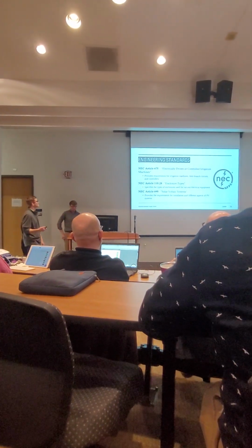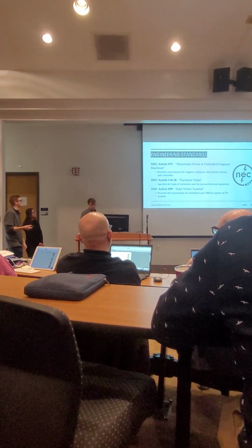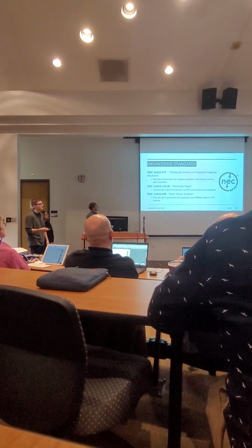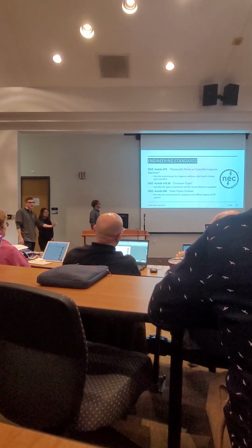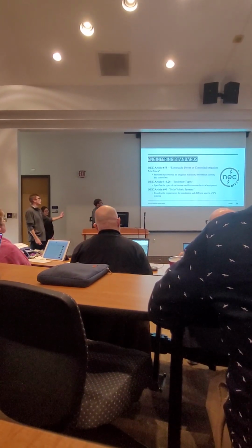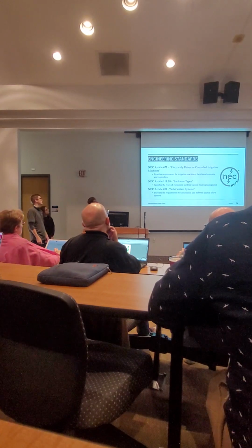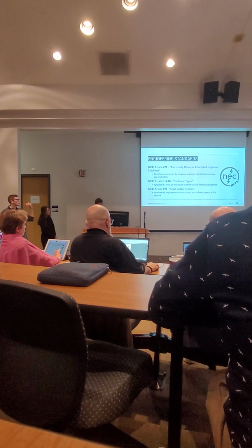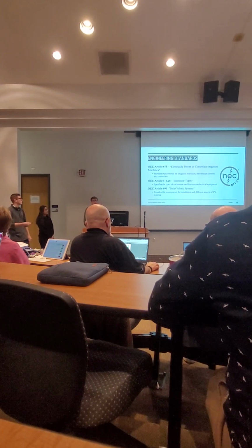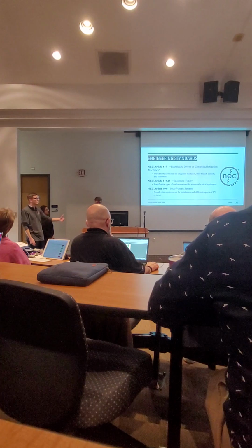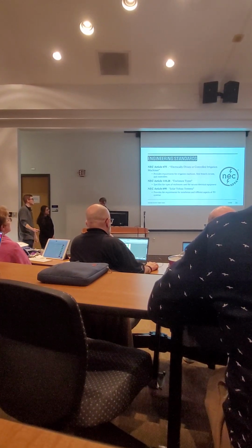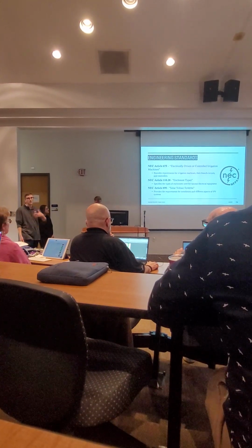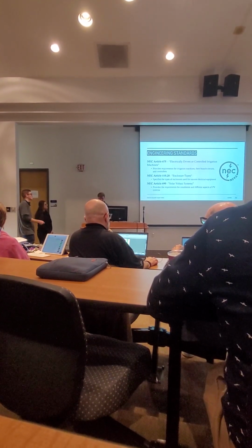So some of the engineering standards we went off of, one of them was NEC Article 675, which talked about electrically driven or controlled irrigation machines, which provided some information on grounding for controls and waterproofing as well. NEC Article 110.28 covers enclosure types, so it gave us the enclosure ratings like rainproof, waterproof, and other descriptions of what kind of enclosure we needed. And finally, we used NEC Article 690, which provided information on solar photovoltaic systems for our solar panel and what we needed to do.